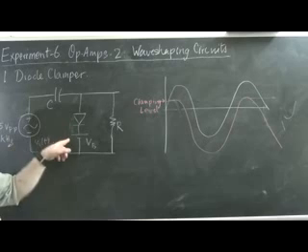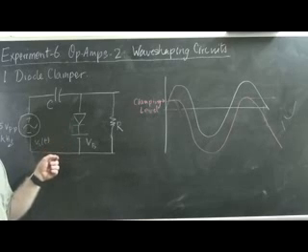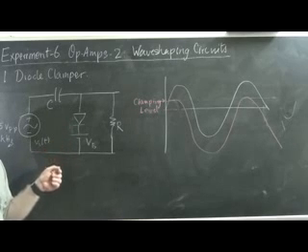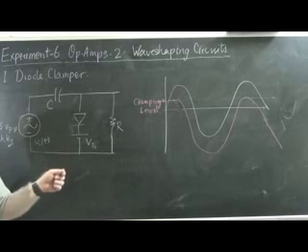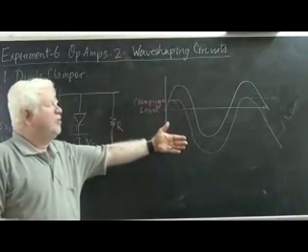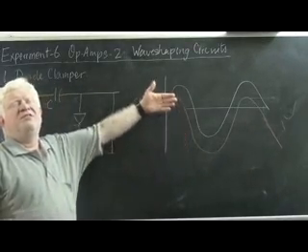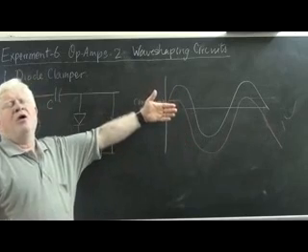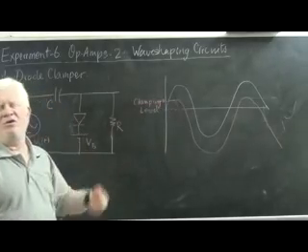You might even be able to have an adjustable source over here and you can adjust that voltage and see how after a few cycles the clamping voltage readjusts itself and the waveform of the output shifts its DC position to adapt to the new battery voltage.